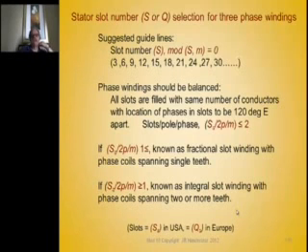You might have cases where one pole has 1 coil per pole per phase, and another pole might have 2 coils for that pole. But that 2-coil pole has to be 120 degrees apart for every phase for it to be balanced. A case of that would be a 4-pole 15-slot motor.